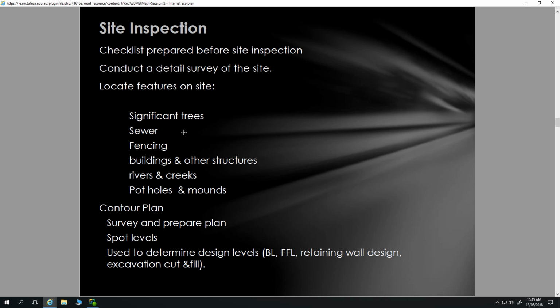We've got significant trees. I'd also look for older stumps as well, and certainly evidence of termites there. They have to do termite protection for all buildings, but with stumps, whether there's going to be anything that comes from that, and excavation and removal of those. I look for things such as underground power that might run to neighbouring properties as well. I think that's about it.